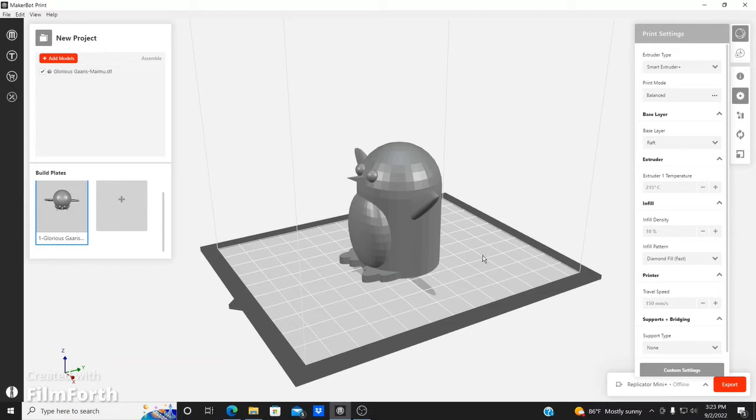That's the melting point. So you have ones that are cooling a little bit down, but still hot enough. It'll be really, really hot plastic that'll still be oozing, but not cool down. So there are different ranges on the filaments out there that you have to follow right away. Because if you don't follow that one, you might clog your nozzle. You will have a failed part that will not ooze out properly, or if you overdo it, it'll burn it. So you have to follow those instructions on the filament right away. On your package, it will say the temperature right away.